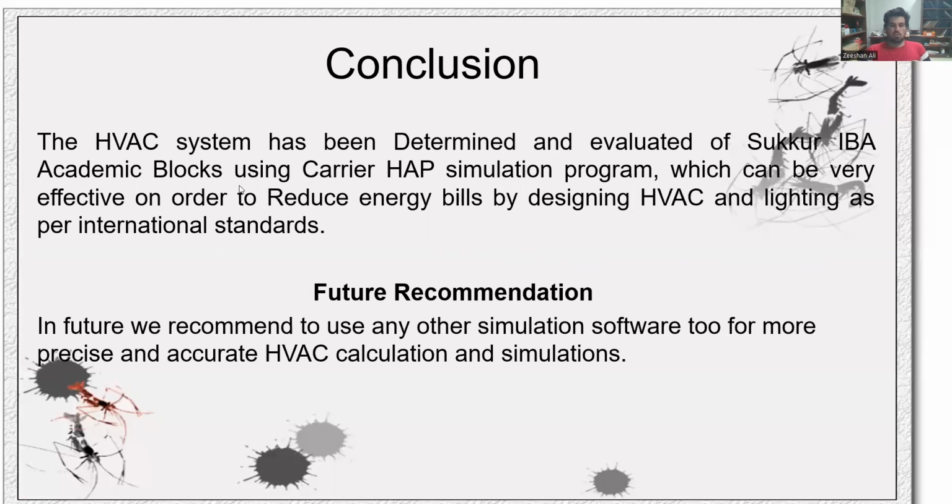So we conclude after that comparative analysis that the cooling system can be reduced to save monthly energy bills. The HVAC system was determined and evaluated for Sukkur IBA academic blocks using the Carrier HAP simulation program, which can be very effective in reducing energy bills by designing HVAC and lighting as per international standards.